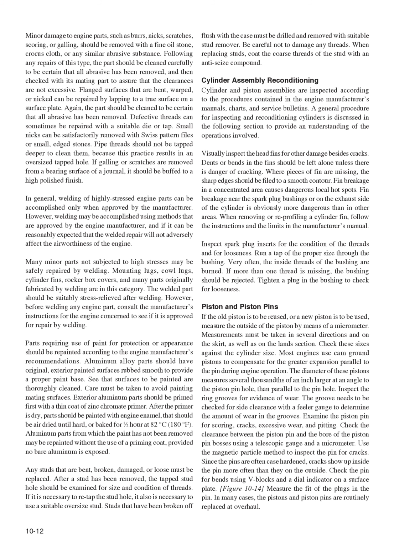The groove needs to be checked for side clearance with a feeler gauge to determine the amount of wear in the grooves. Examine the piston pin for scoring, cracks, excessive wear, and pitting. Check the clearance between the piston pin and the bore of the piston pin bosses using a telescopic gauge and a micrometer. Use the magnetic particle method to inspect the pin for cracks.